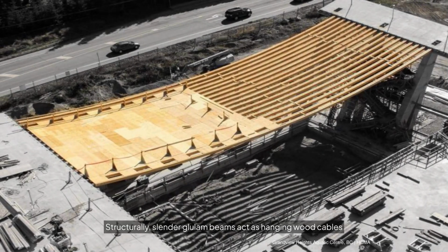Structurally, slender glulam beams act as hanging wood cables between concrete buttresses, achieving a span of over 60 meters. The roof's curvature is made of glulam timber beams acting in tension, like timber cables. Using wood in this way was unprecedented. The design and engineering team thought they would need steel cables to support this sweeping form, but in a bold move, they realized that engineered wood alone could support the span.